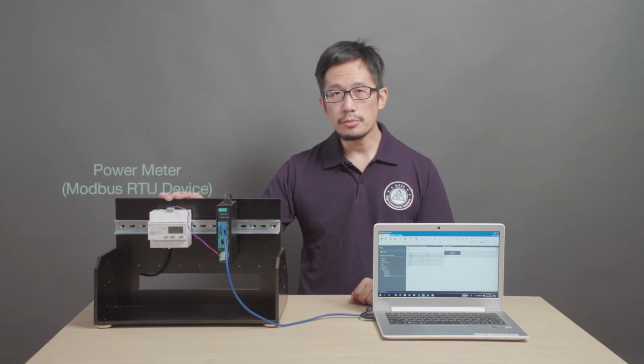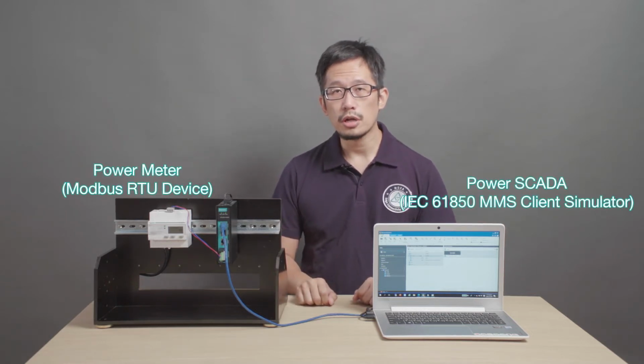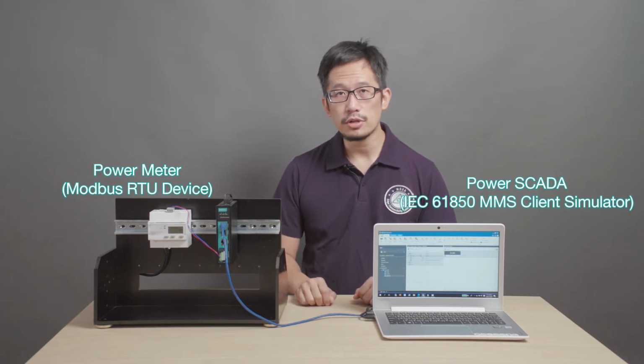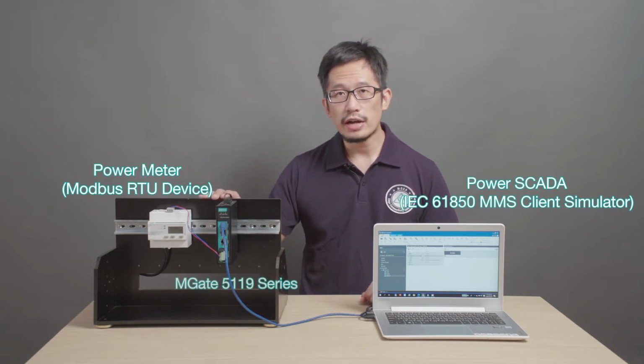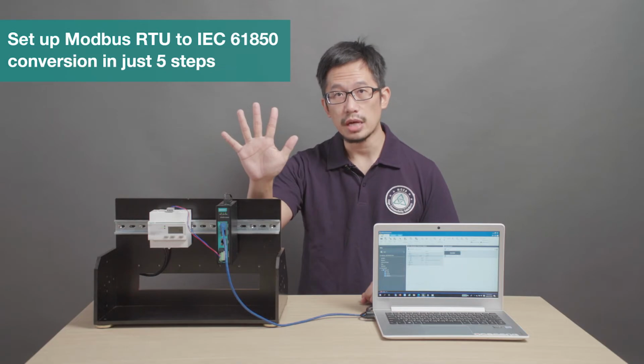To connect this power meter to our power SCADA, we need to convert Modbus RTU protocol, which this power meter uses, to IEC 61850 protocol, which our power SCADA uses. So we're going to put our MGate 5119 series gateway in between them to handle the protocol conversion for us. And I'm going to show you how you can set this up in just 5 steps.